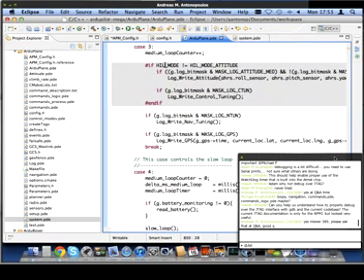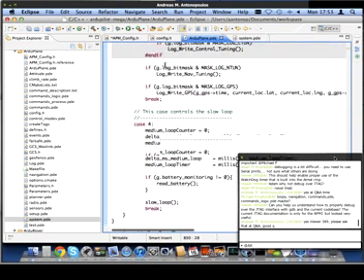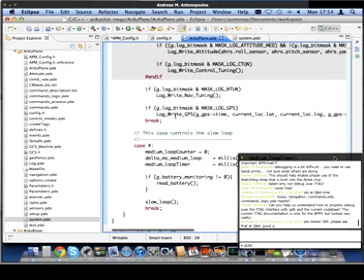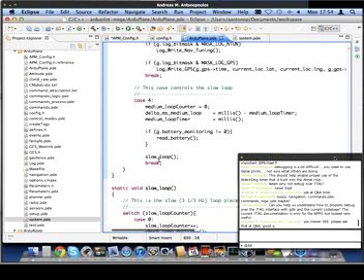Then the next one, we have the navigation tuning check, and another one. This doesn't do very much apart from write a bit to the log file. So at 10 hertz, we write out some log information to the data flash, and finally we read the battery at 10 hertz down the bottom there.